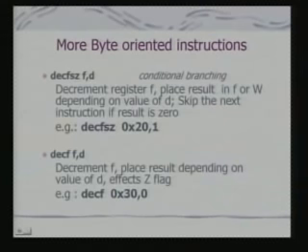The next instruction which has been fetched cannot be executed. So, that instruction has to be replaced by NOP or no operation. So, effectively this instruction would now require 2 cycles for execution. That is, when the result is 0, this instruction will actually require 2 cycles for execution and not just 1 cycle for execution.